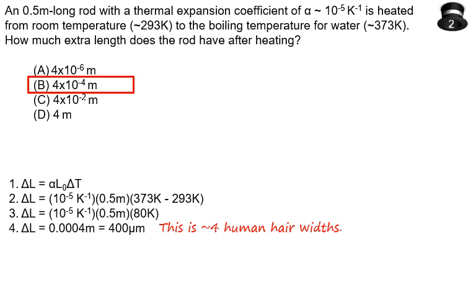So this is why you may not have really noticed this linear expansion much in the past: you need a relatively large change in temperature if you want to see this change in length for a small object. For a bridge, it's a bigger deal because a bridge is a very long object, and so you still have a small delta L over L, the fractional change in length is still small, but the absolute change in length is significant. So you need to include these expansion joints to take into account that little bit of extra play.